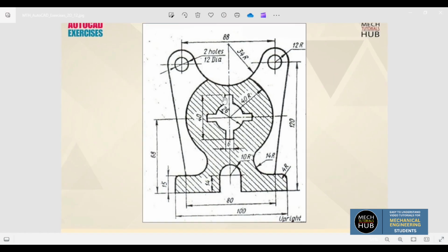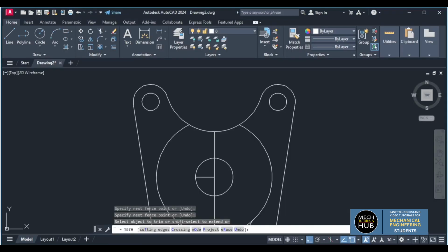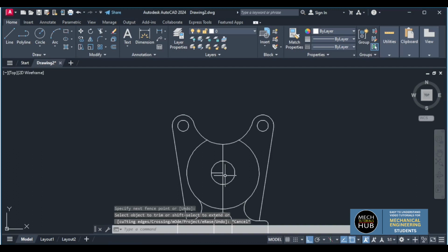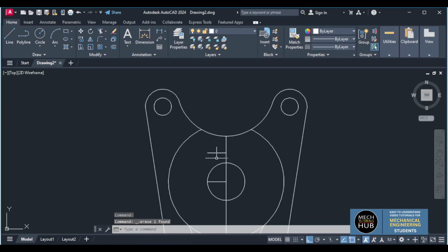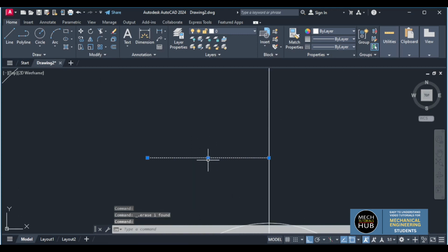Before going for hatching, here this keyway or the gear kind of representation needs to be marked, which is at an offset distance of 40, means 20 on either side, with a width of 6, 20 on both the sides. So offset this up to 20 on both the sides. Sorry, this side is not required. Actually I can plan only one side, then I can easily,